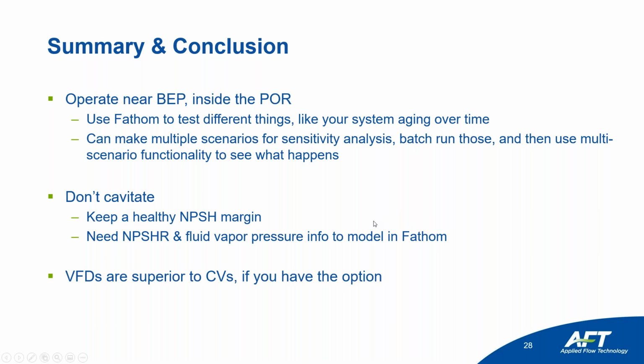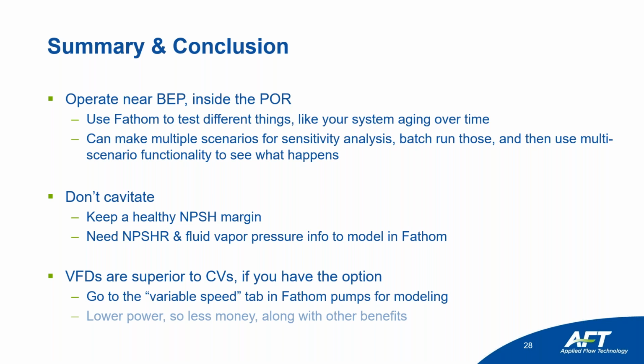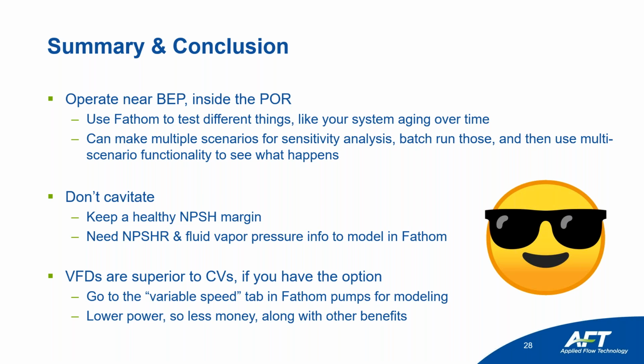Finally, VFDs are superior to control valves. If you have the option, again, I know obviously mine is a very simplified system, but it shows you the idea. If you can use a VFD in your system, it's going to be much better for you in the long run. And you get that rebate, so you don't have to worry about the cost. In Fathom, how you do it is you go to the variable speed tab in Fathom pumps for modeling. Lower power, less money, along with other benefits. Mr. Cool Guy shows up.